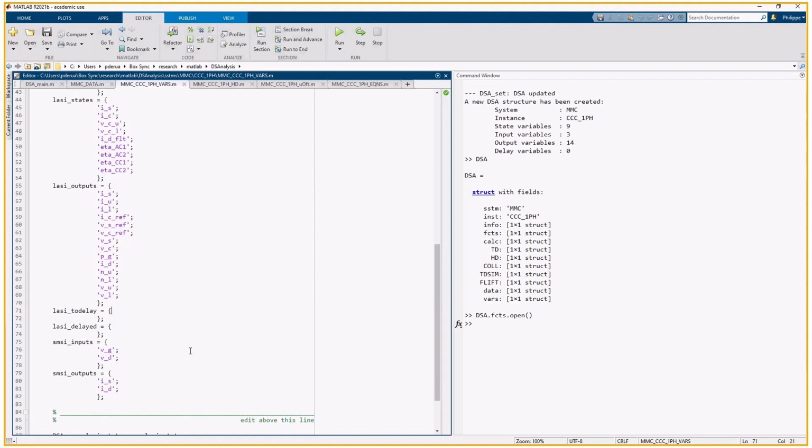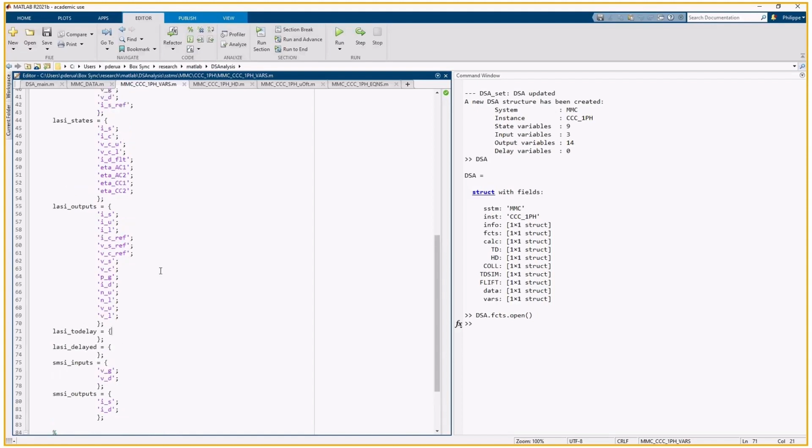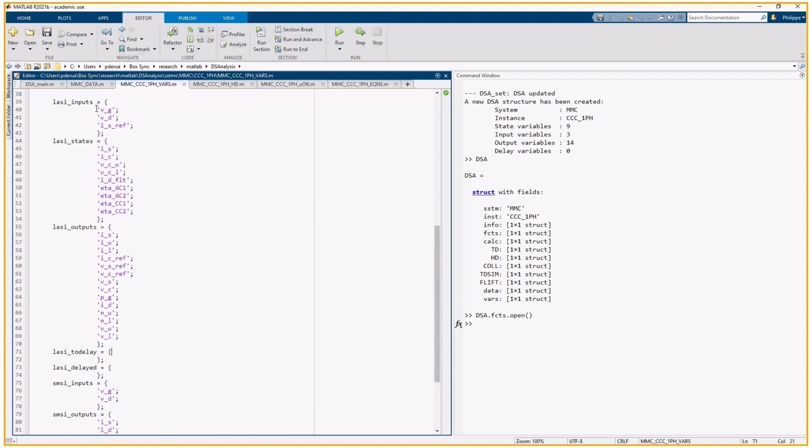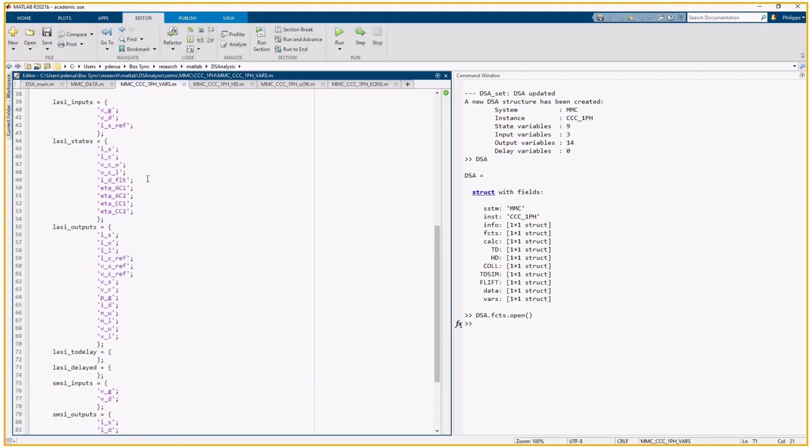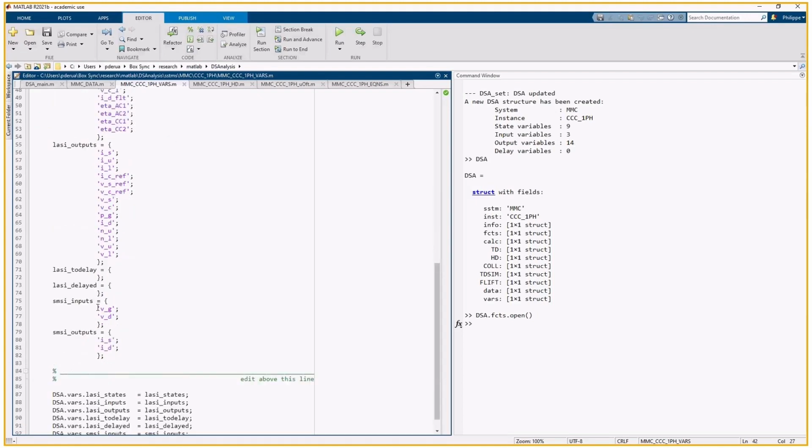However, we will start talking about calculation of eigenvalues, calculations of frequency responses. This is when linearization comes into play. The system that we will consider now, this single phase MMC, is nonlinear. So after linearization, we will be able to obtain a linearized state space representation. This linearized state space representation is defined from a given set of inputs to a given set of outputs. Although I have, for the large signal model, 3 inputs, I am interested in only 2 of them.